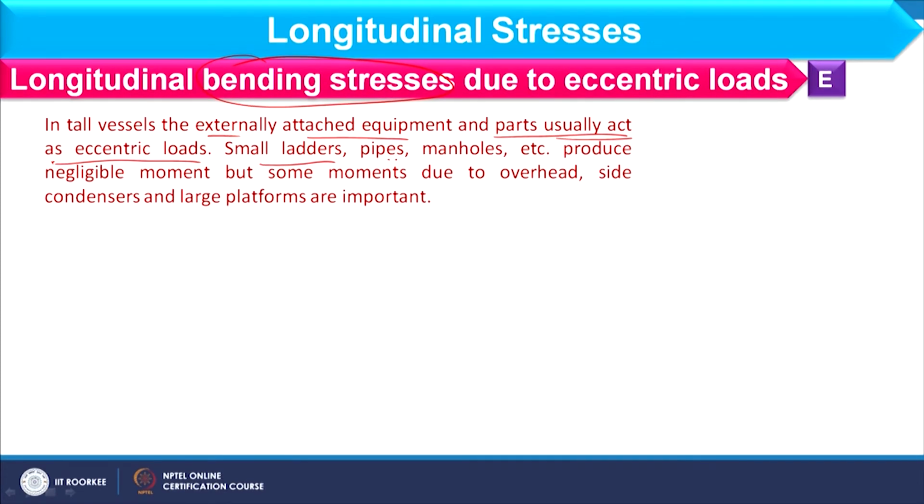Small ladders, pipes, manholes, etc. produce negligible moment, but some moment due to overhead side condensers and large platforms is important. So, usually we neglect the stress generated due to eccentric load.